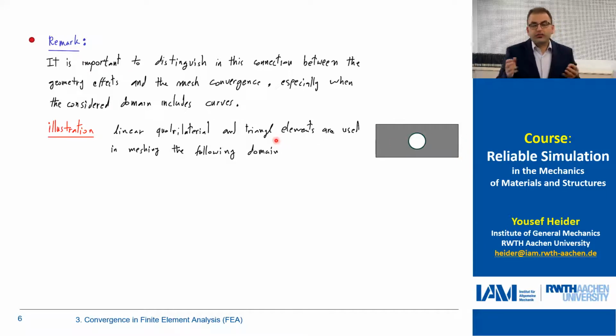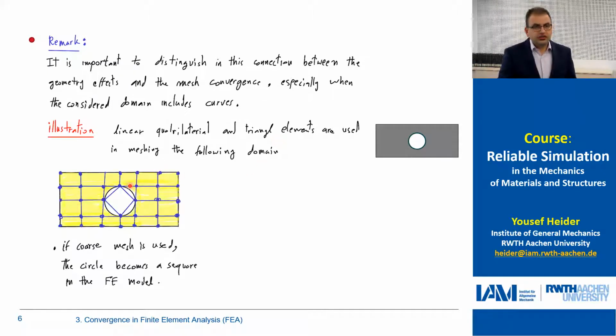We assume that we have a load on it, which is not so extreme, so we don't really have stress concentration. So initially we don't need a lot of elements. We can choose only a few elements. Let's choose this initially, big elements. We can make a mix of quadrilateral and triangle elements.